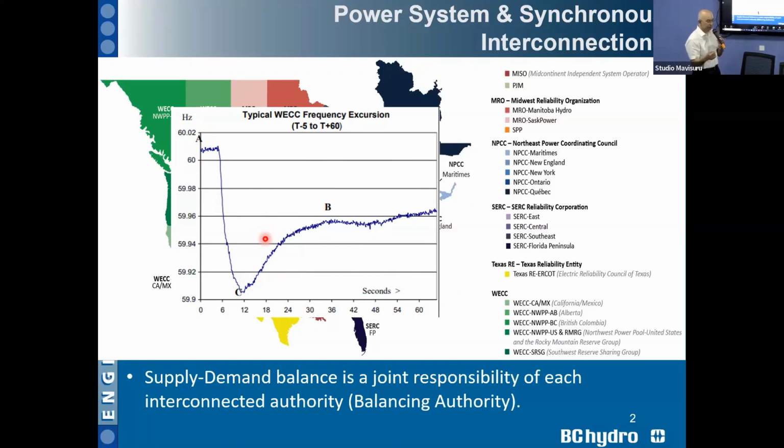I know that in some systems you will have one or two frequency control machines, whereas we don't have that case. We do not have frequency control machines. I'm repeating it, we do not have a frequency control machine. Every machine in the system is operating on the exact same droop of 5%, not even 4%.